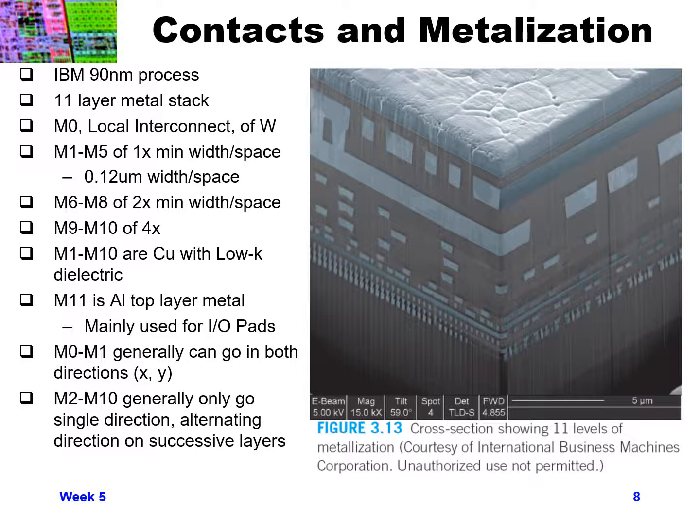The other thing in this particular process technology, the lower levels of metal were copper with a low K dielectric. The top layer of metal was aluminum, and again here you're choosing a different metal. Even though aluminum has higher resistance, at least in their estimation it was better for connecting up, since the top layer of metal had to connect to the pads and the package. Aluminum was deemed better to use as a connection to the package than copper, and so they went with a slightly higher resistance in order to get better connection properties. So again, trading off different parameters depending on the use and connectivity between layers and between package and chip, and so on. These are the various trade-offs you need to think about as you're selecting